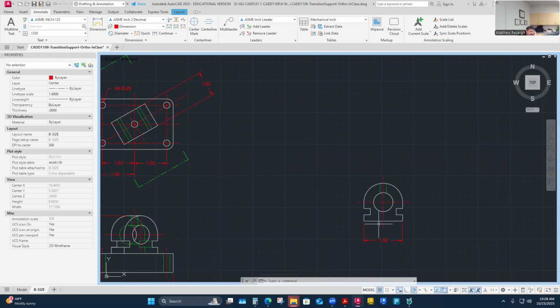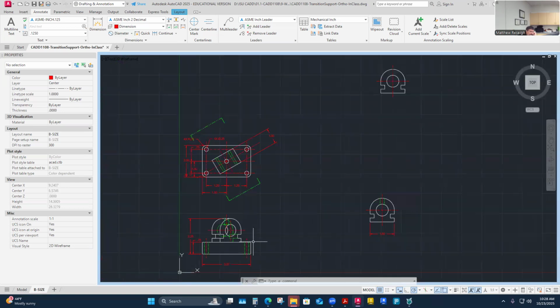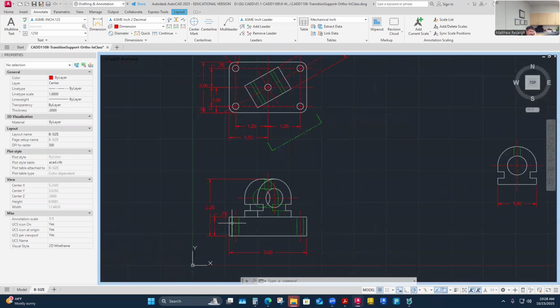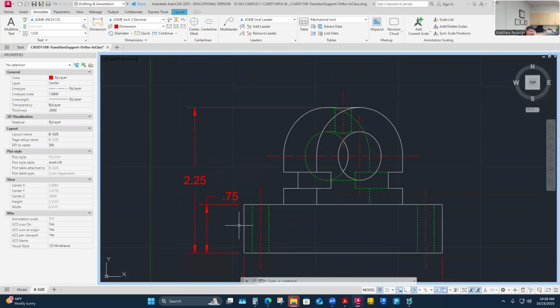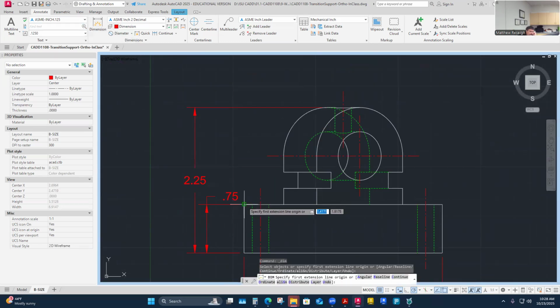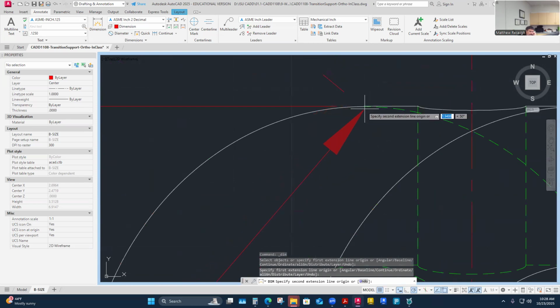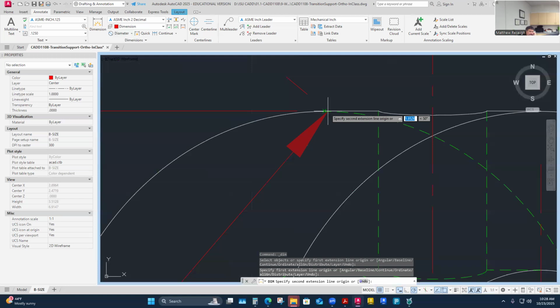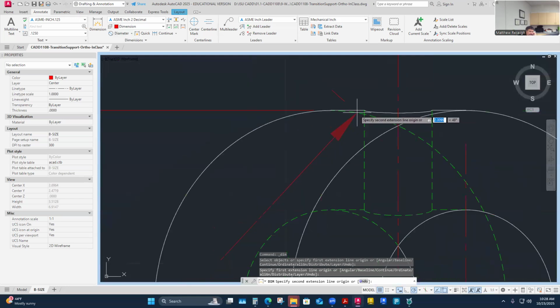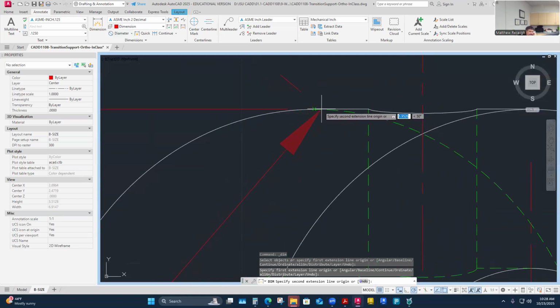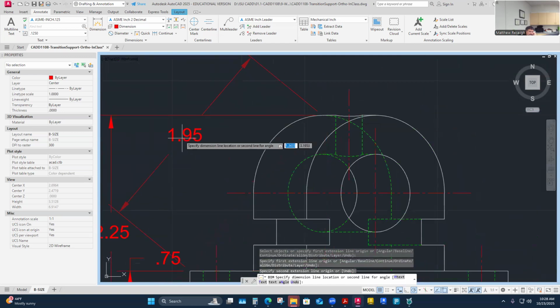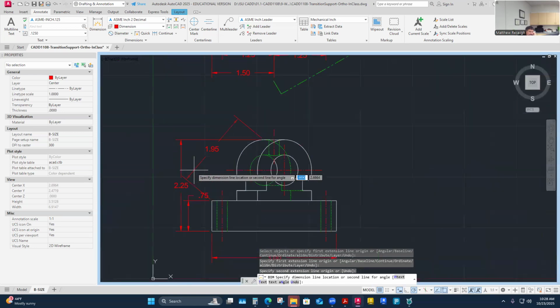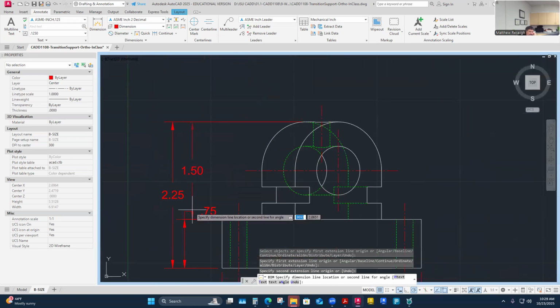I just need the thing in the other direction, which is this direction. Problem is pulling that, where's the best place to pull it? Well, I don't know. I think I'm going to pull it here, up to this quadrant, and make sure I don't grab some weird place on that weird ellipse that I've got, but up here at the quadrant where it's truly flat. I think it's where these two would meet. Yes, that seems right. If I get the wrong dimension, I will know that I grabbed something wrong, but it's an inch and a half, yes.